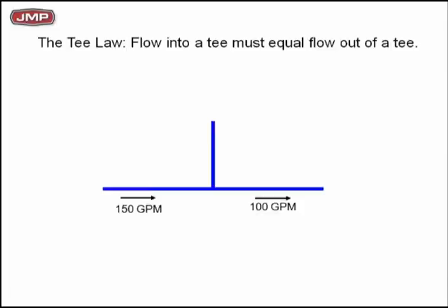Place to start. I kind of like calling this the good Lord's T-law. What goes in a T has to come out. And when I put two T's together, I have the common pipe and a primary secondary setup. So let's just go down to the individual T. Let's keep this real simple. This is not a complex theory. If you just look at the T-law and work your way through it, it becomes pretty simple.